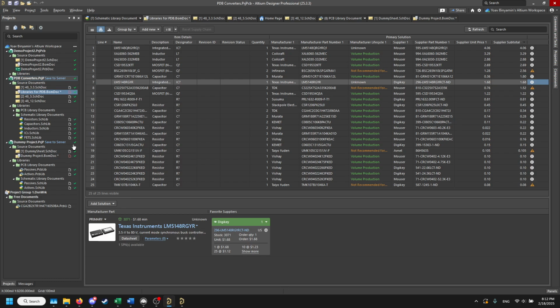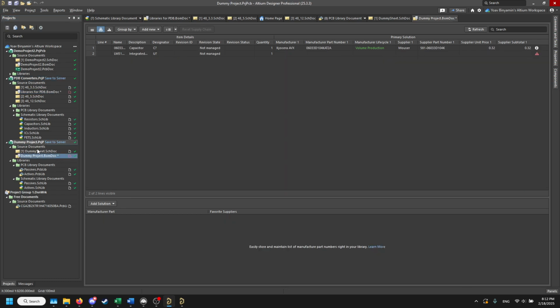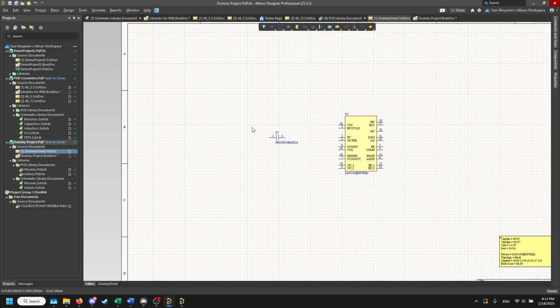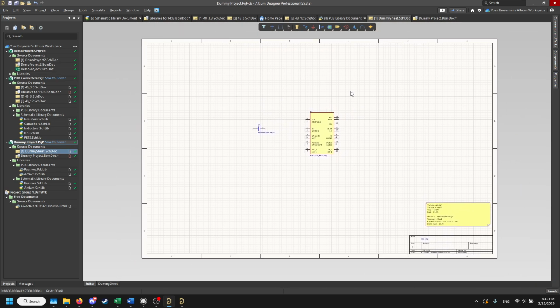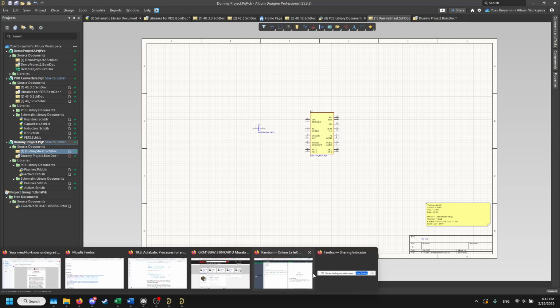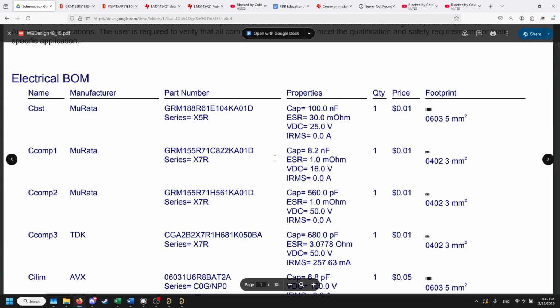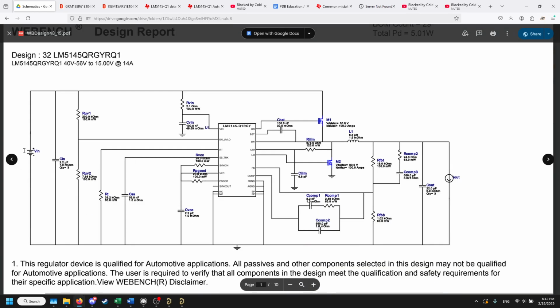So now I'm gonna go over a little bit how you should go about making the right looking schematic. Most schematics are laid out with voltage or inputs on the left and then outputs on the right. It might be different in Japan or Israel because they read from right to left, but in the United States of America we read from left to right. So the inputs are going to be on the left, the outputs are going to be on the right.